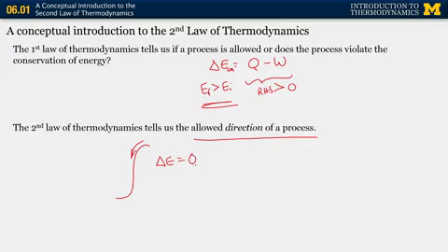And we can, in fact, check the box that the criteria for the conservation of energy is met. But we can't tell from this analysis whether the water should be going down or should be going up. And again, intuitively, we know the water has to go down. So again, what does the second law do? The second law tells us what is the only allowed initial state and the only allowed final state. Okay, so that's some pretty advanced second law analysis.